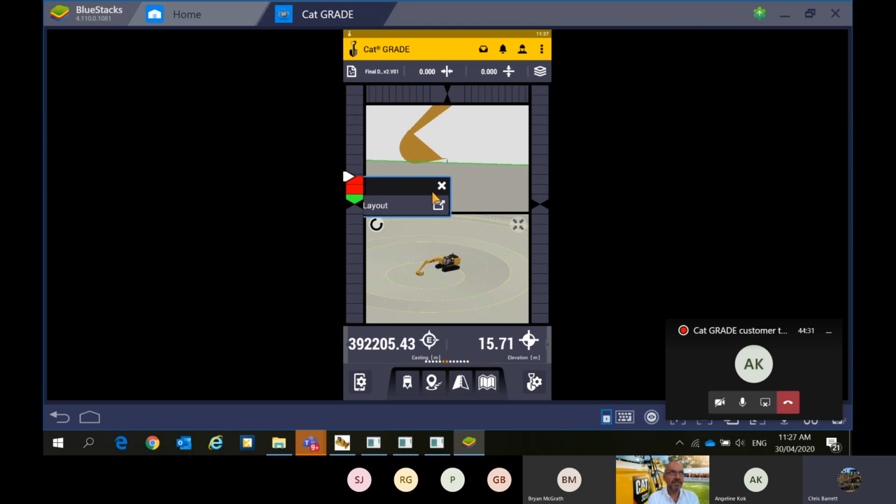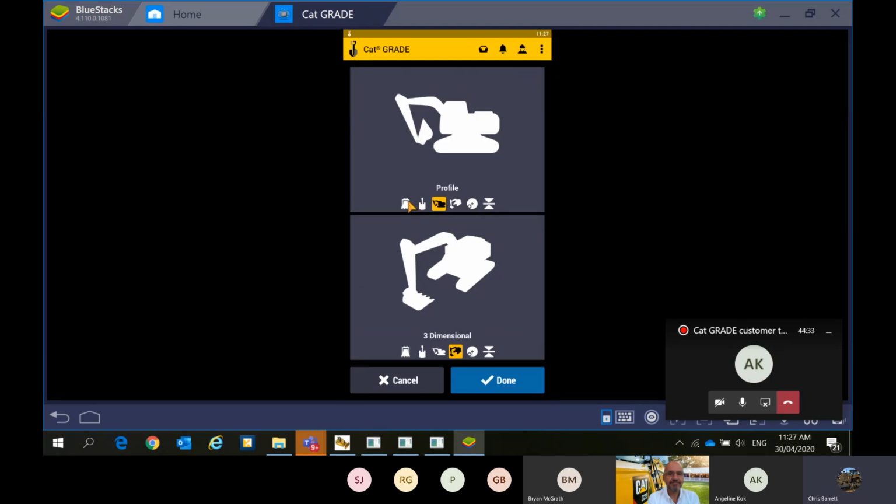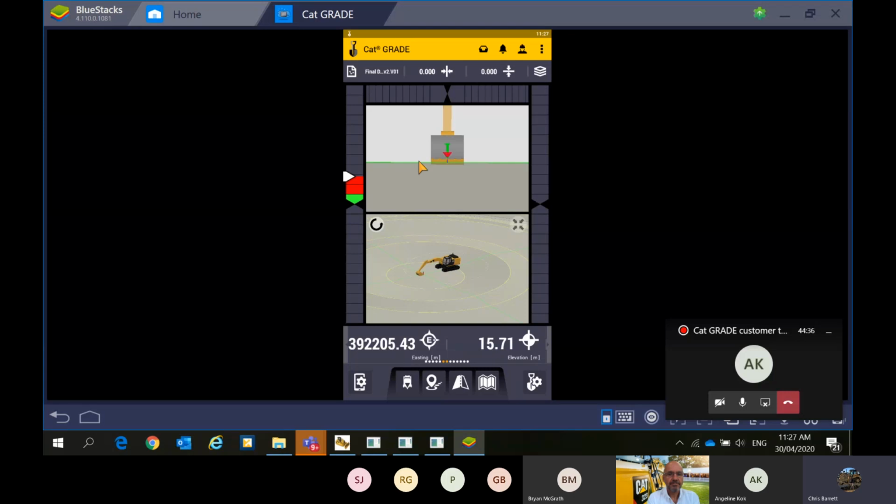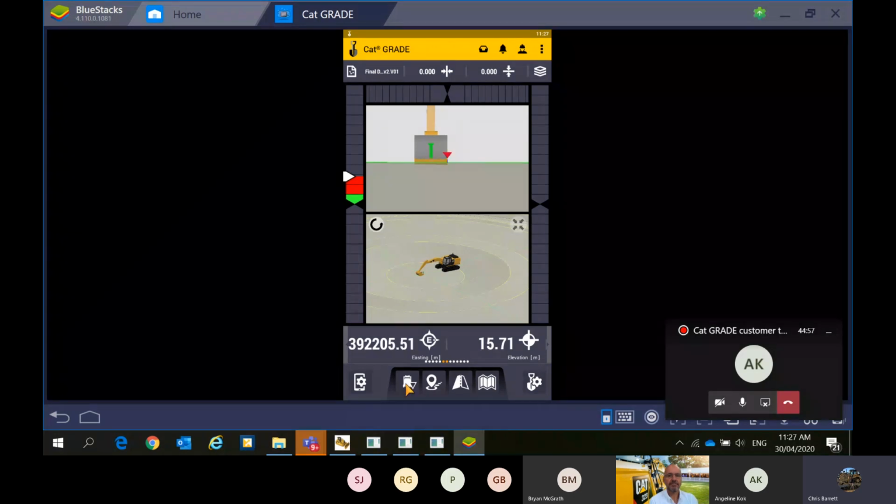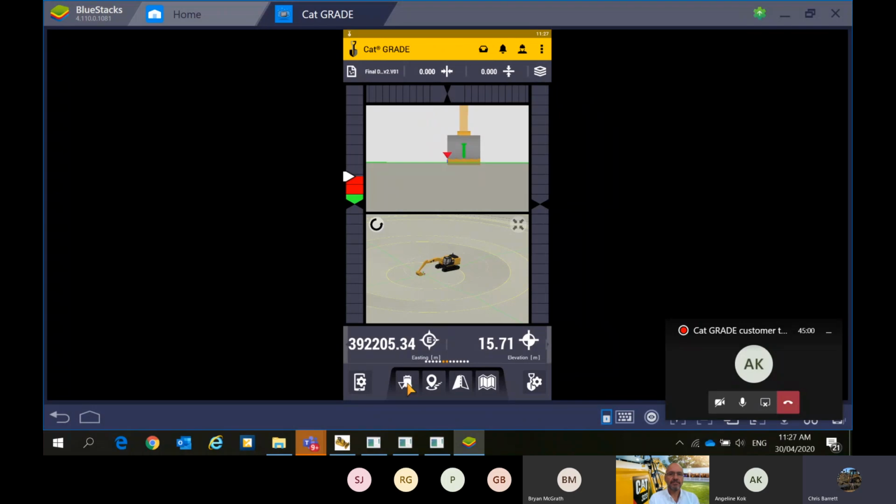So we're checking for accuracy is what you're saying? Correct. And there are a couple of different ways to do that. I'll change the focus view that we have there. Within the system, we can change the focus point, which is an easy and nice to use feature. You can see this little red dot in the center of the bucket. That is where we're getting these values from. If I change this from left to right, that's going to change those northing, easting and elevation values.